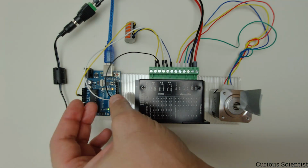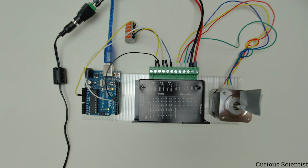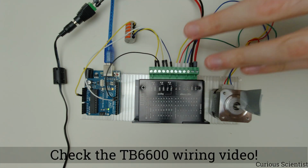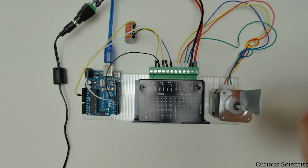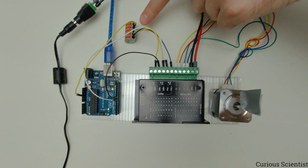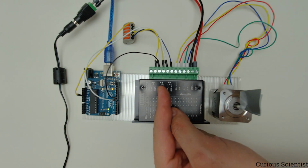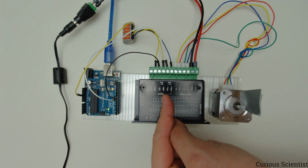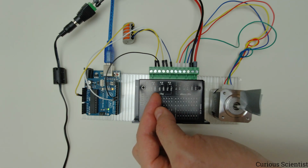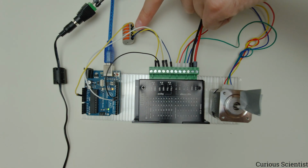You can see there are only 3 cables connected to the Arduino, and I have a video on this, so please check that if you really want to know the details of this connection, but I quickly explain how it works. We have a 5-volt connection here, which is put in this terminal, and then 3 cables are going out to each of the positive pins of the signal pins. So the enable plus, the direction plus, and the pulse plus are connected to the plus 5 volt.